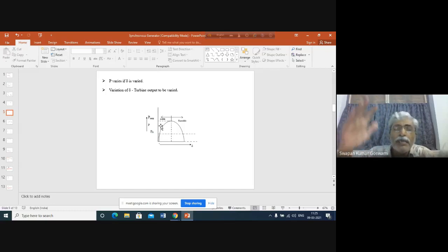But obviously, it cannot decrease the speed in a single step to synchronous speed. So gradually the speed will decrease, and somewhere here, after crossing the input power line, the speed of the rotor and the synchronous frequency of the infinite bus will become the same. Okay, am I clear? That means the input power line has been shifted up. As a result, delta is increasing.